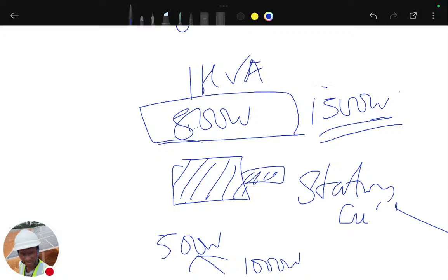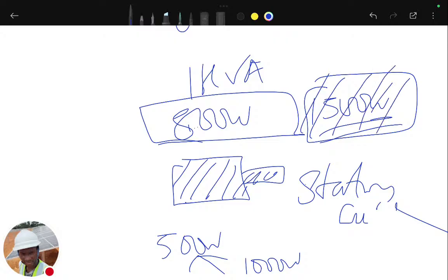So that's why they leave this surge rating, like an allowance for devices such as a fridge and so on, so that when they start, they don't spoil the inverter. But you're not supposed to operate in this region for too long. At most 10 seconds. Operate around that region and go back to the normal rating. I hope that clears this up, Edwin.